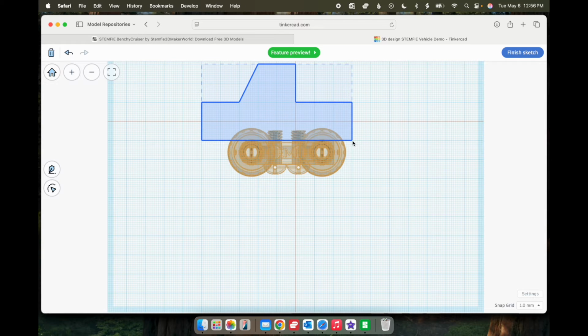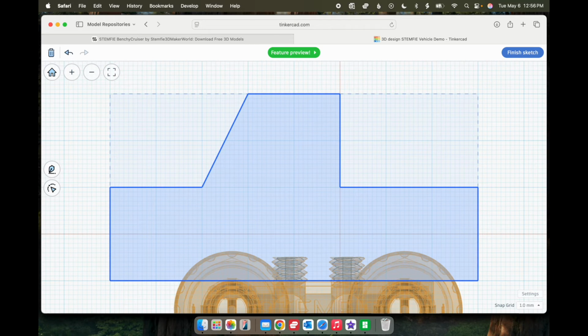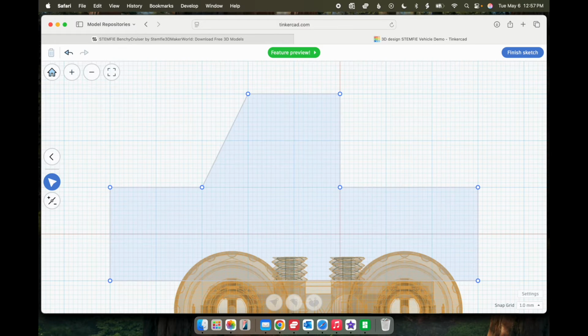So you can see I've drawn a very simple pickup shape outline. Tap the F key to focus in on it. On the left-hand side, we'll click the Edit icon. Notice you can also tap the letter A on your keyboard as a shortcut. Now we have all the control points that we can change. So let's say I want to make the front of the truck rounded. Down below, I can change that point from a corner to smooth. And I can also use the number 2 to do that.